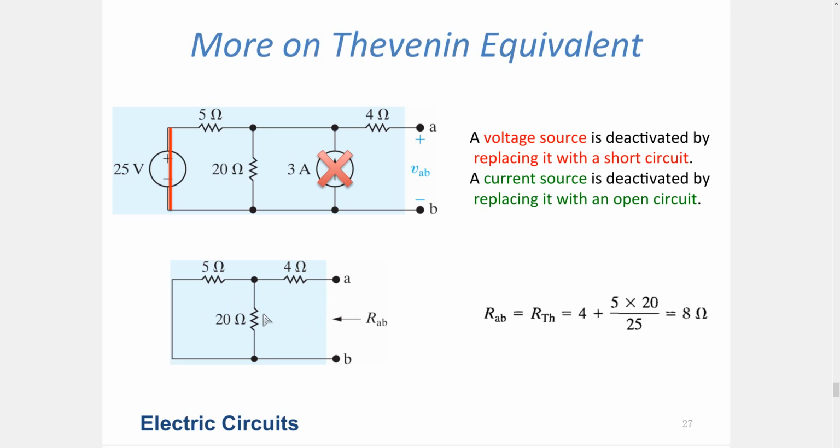If there are dependent sources, then you have to connect either a current source or a voltage source, and you have to find that V over I value in such a way that it will give you the equivalent resistance looking into the circuit nodes A and B. That will be your Thevenin resistance. Once you know these 2 things, you can easily construct your model. Now, in practical circuits, this is easy. 2 measurements and you have it. But in theory, you have to solve the circuit, okay?